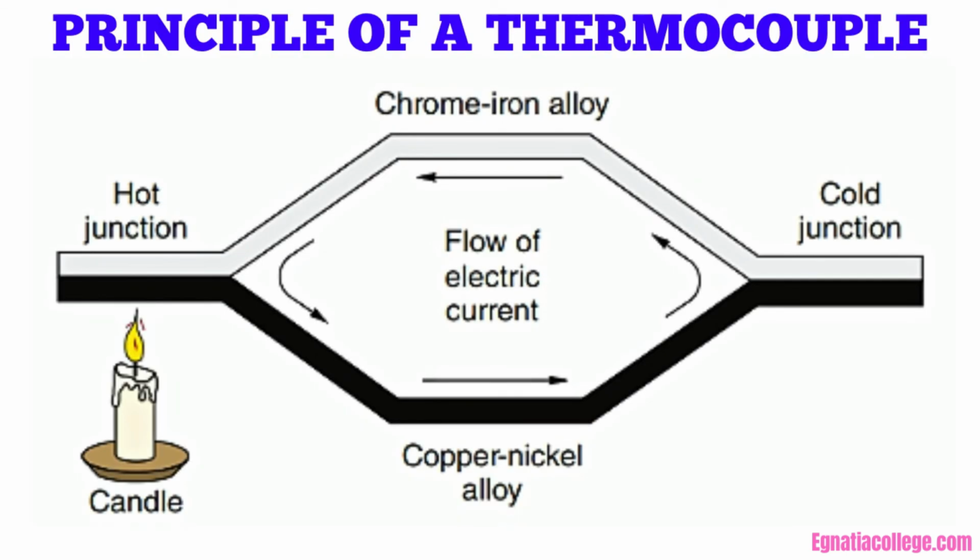Thermocouple. In systems that have a standing pilot, a thermocouple holds open a gas valve pilot's solenoid magnet. A thermocouple consists of two dissimilar metals connected together to form a circuit. The metals might be iron and copper, copper and iron constantan, copper-nickel alloy and chrome-iron alloy, platinum and platinum-rhodium alloy, or chromel and aluminum.